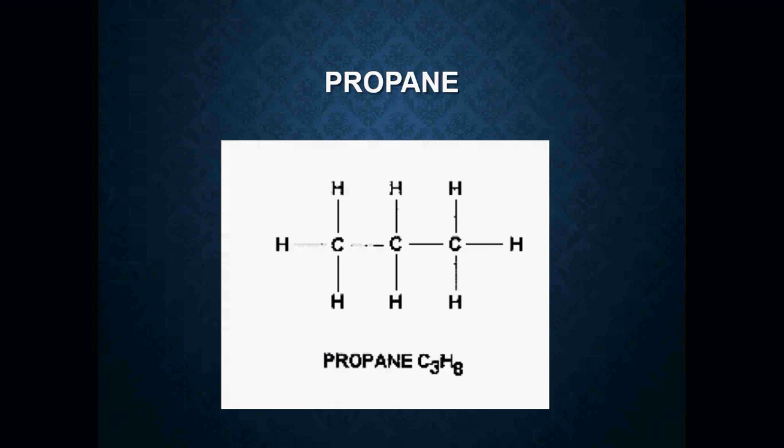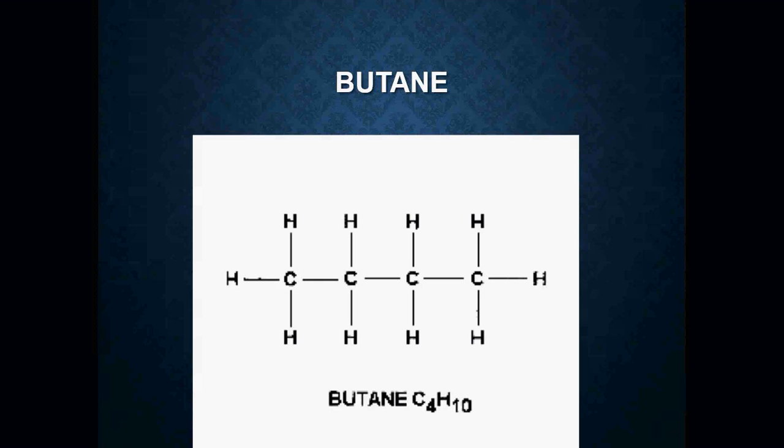Ethane, propane, they're heavier. They may not necessarily just rise up into the air. They'll sink. They'll sink to the floor because they're heavy. Look at butane here. Butane, that's a heavy gas. You got 4 carbon atoms to 10 hydrogen atoms. If there was a butane leak, it's going to pool to the ground. It's going to settle down on the floor, and then as it pools up, it's going to rise steadily up, up, up, to eventually maybe where you'll actually smell it.